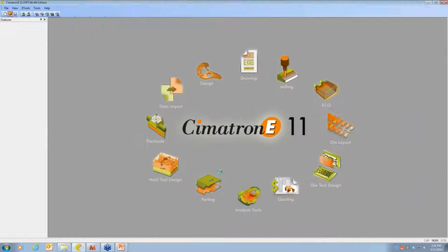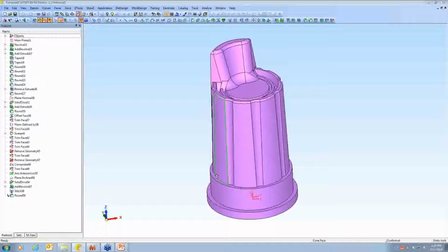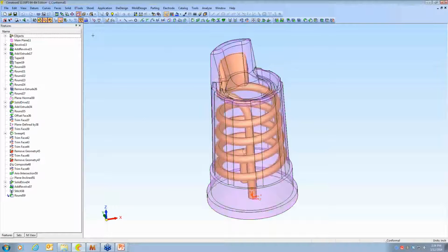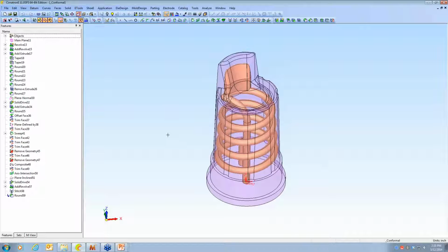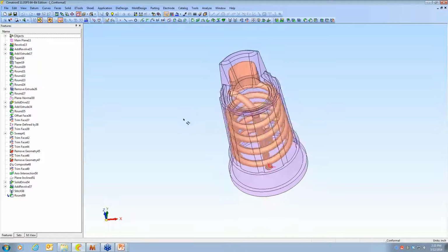Another topic that I should really touch on today is what is known as conformal cooling. The mold industry is always looking for new ways to optimize cooling, especially in tall cores or moving slides. And traditionally, these are cases where baffles or bubblers up into the core are going to be used. But using those types of components is really just a compromise. It's based on ease of manufacture. In an ideal world, the cooling circuits would often mimic the part contours, and we wouldn't be limited to round channels. Any shape would be possible.